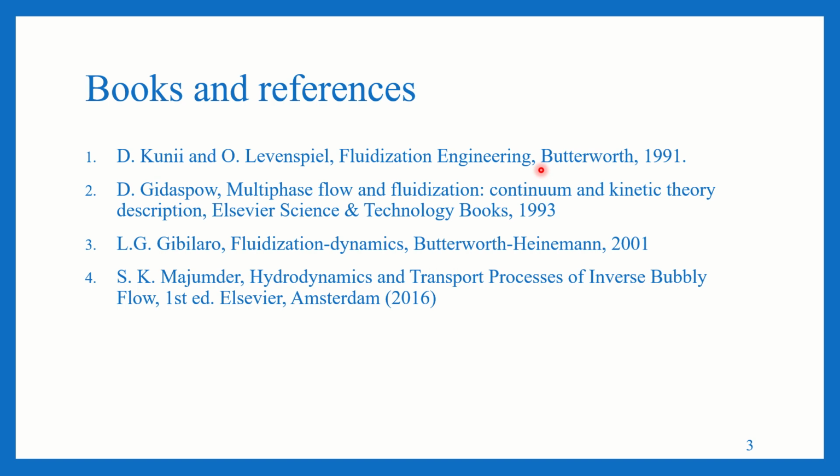similar to that for the gases, we call it kinetic theory of granular flow, KTGF. So by using that, we model the particles, that is solids, inside the fluidized bed as a continuum. So solid would be one continuum phase and the fluid would be another continuum phase. So that is one aspect of modeling the fluidized bed. That is best described by Gidaspow, where he implemented that KTGF, that is kinetic theory of granular flow, similar to kinetic theory of gases.